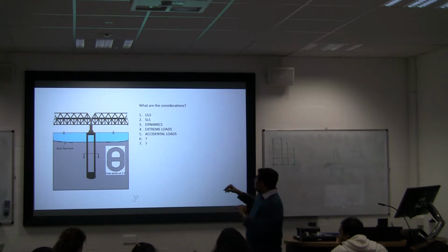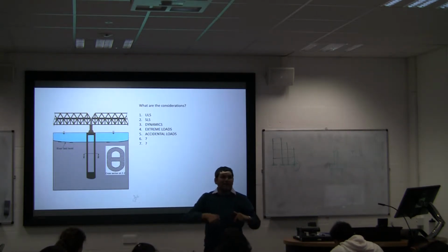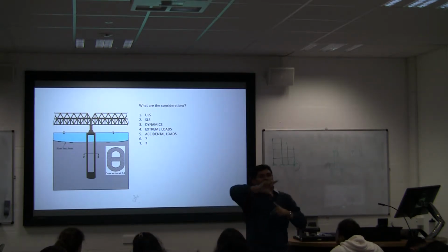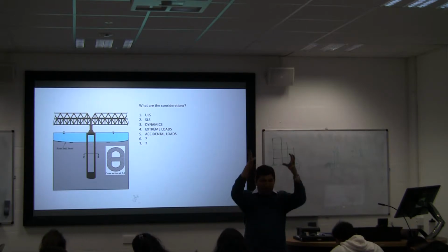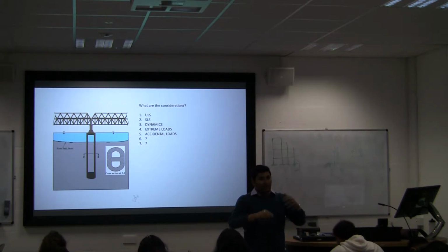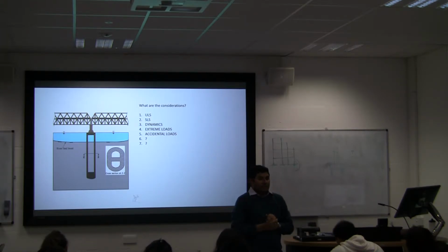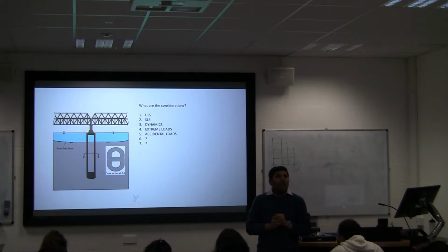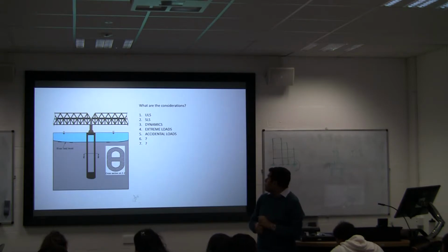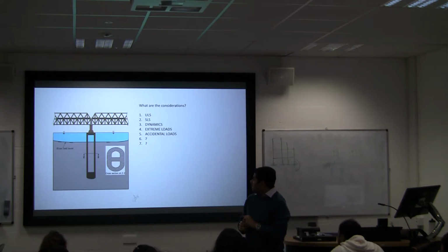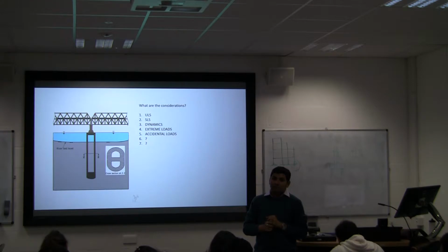So what I am doing here is, first, to know the maximum vertical load, lateral load, and moment load. So VMH: maximum vertical, lateral, and moment. Right? Second is deformation. How much deformation would you allow? What happens if it deforms? Say on an earthquake, it deforms a bit. What might happen?